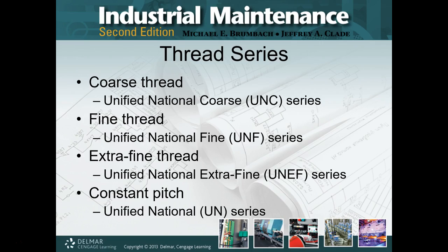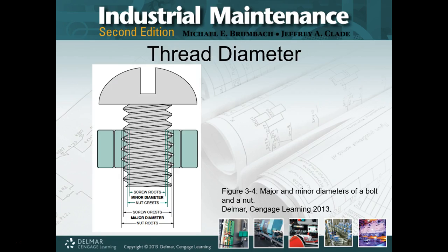For me, because of everything that I've bumped into, most that I've seen is coarse thread for fasteners like flange gaskets, that kind of thing. It's always coarse thread, and even when you are putting together pump housings and such like that, it's usually a coarse thread. The fine thread, extra fine thread, is usually as you go into more delicate and refined equipment.